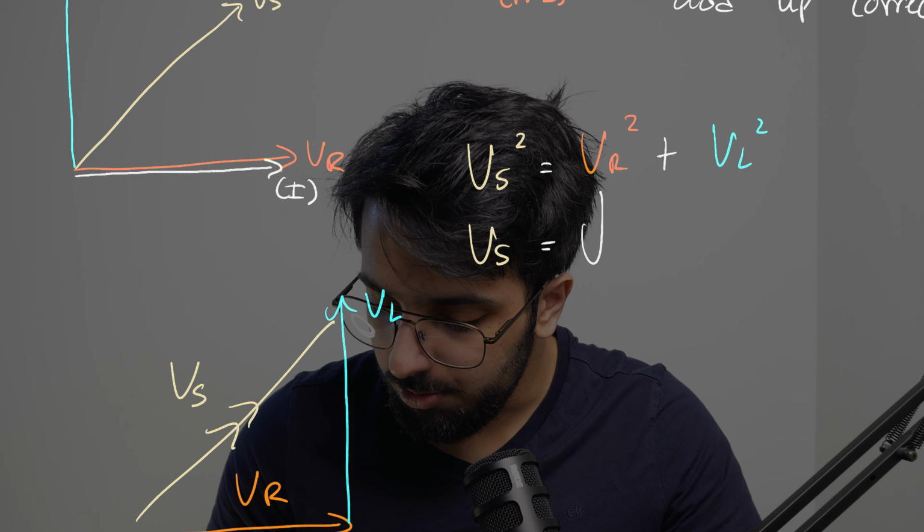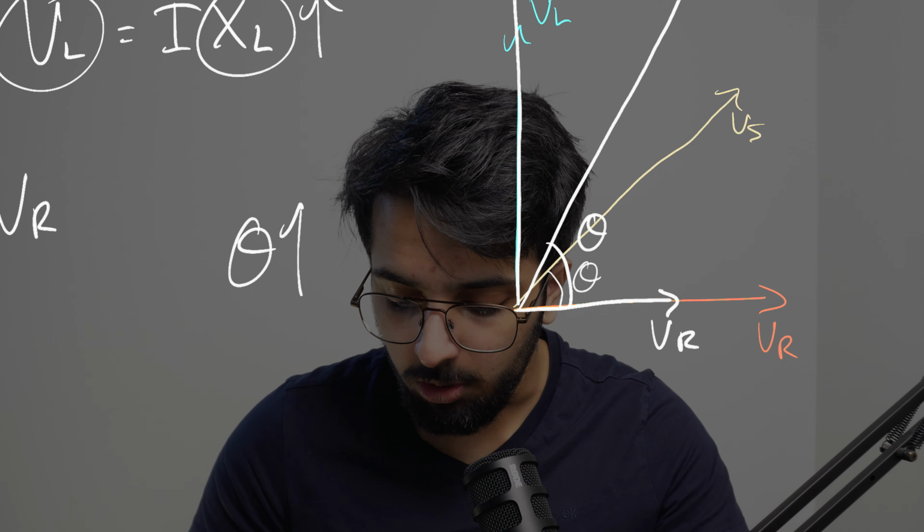And so if we look at our phasor diagram, if we were to copy this down, bring this over here, if the voltage across our inductor has increased, let's make it bigger, so this is now the new VL, and the voltage across our resistor has decreased, therefore, our new Vs is going to look something like this, okay? And so as you can see, we have a much bigger phase angle, okay? So our phase angle will increase.